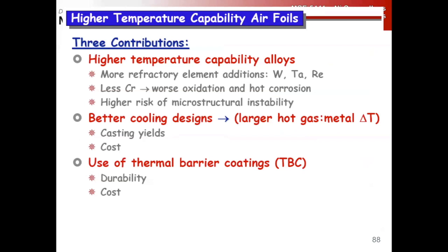It's a jet engine. The problem is the gamma prime solvus in cobalt is so much lower than in nickel. So people haven't been able to take advantage of developing really practical cobalt superalloys yet. But we're really running out of the room we have to increase the temperature range of the superalloys themselves.